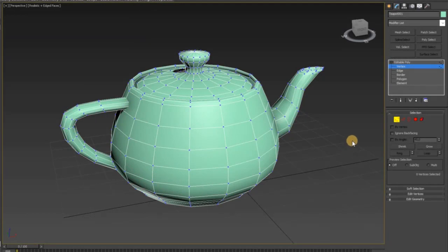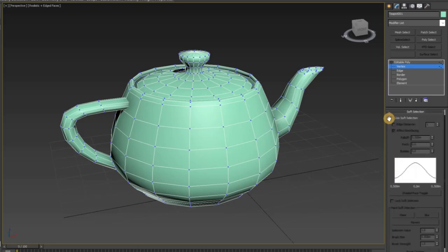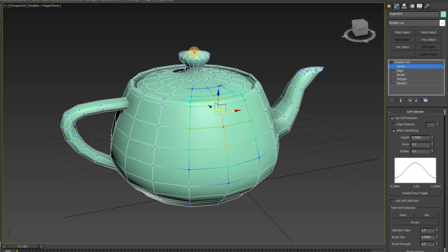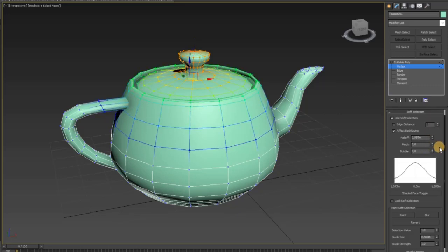Soft Selection rollout. This rollout enables you to display a soft selection on an object. The options in this rollout are used to affect the action of movement, rotation and scaling at sub-object level of the editable poly object. To activate this rollout, you need to select a sub-object level. Next, to activate the other options of this rollout, select the Use Soft Selection checkbox.